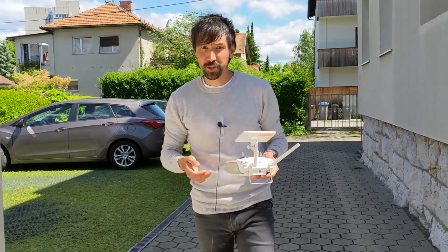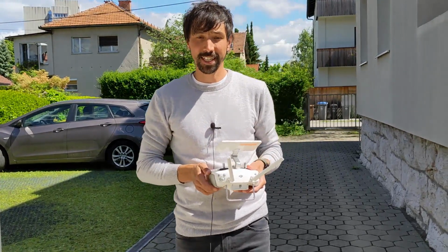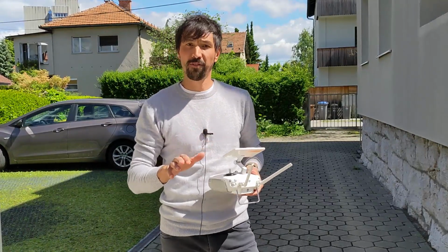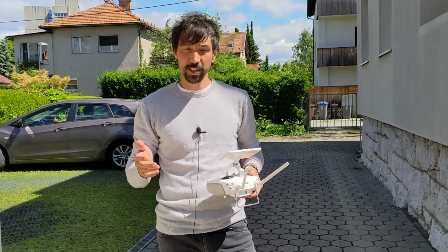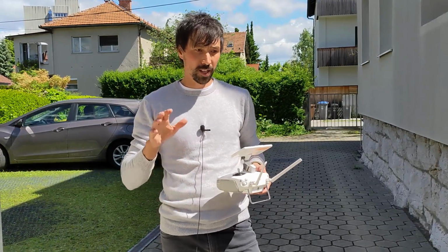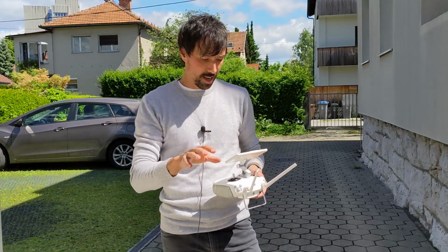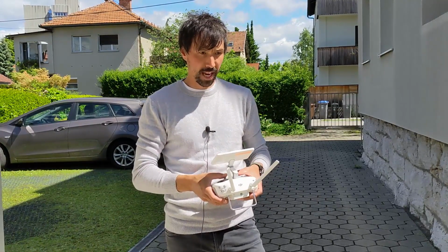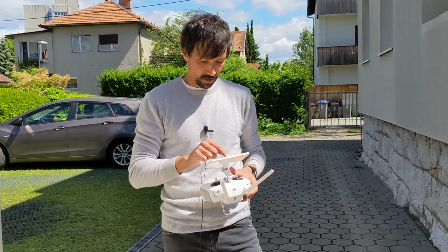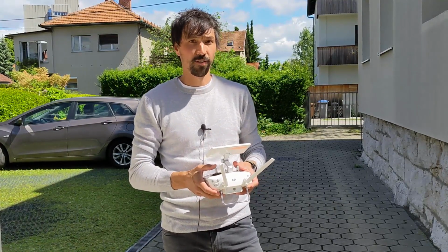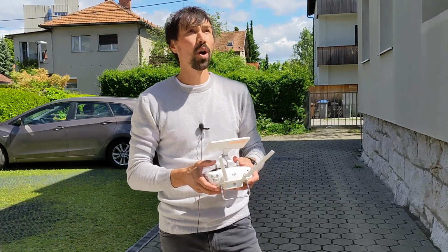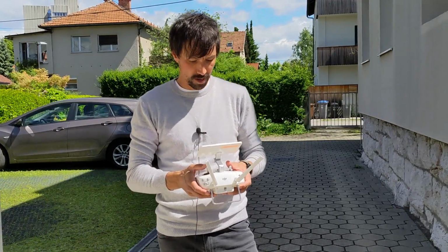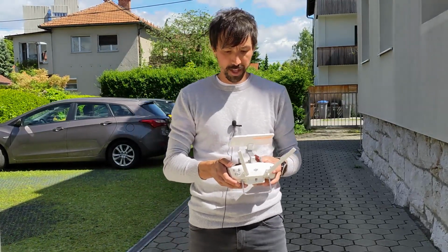One option to set your camera parameters is to try the best possible value before you go flying. What you need to do is have your drone. You could have the drone landed on the ground and check the values, but better is to turn on the propellers, take off, and start your flight manually. I will go up to, let's say, 10 or 50 meters to have a more realistic view. Okay, right now I'm at 50 meters.